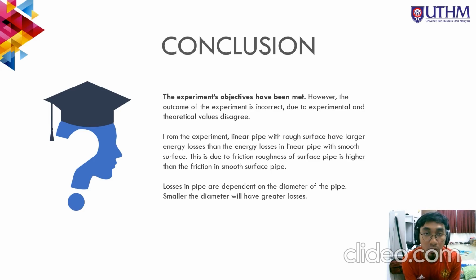From the experiment, we also know that losses in pipes are dependent on the diameter of the pipe. The smaller the diameter, the greater the losses. Besides, losses in pipes are also dependent on the flow rate. When the flow rate is higher, losses will also be higher.